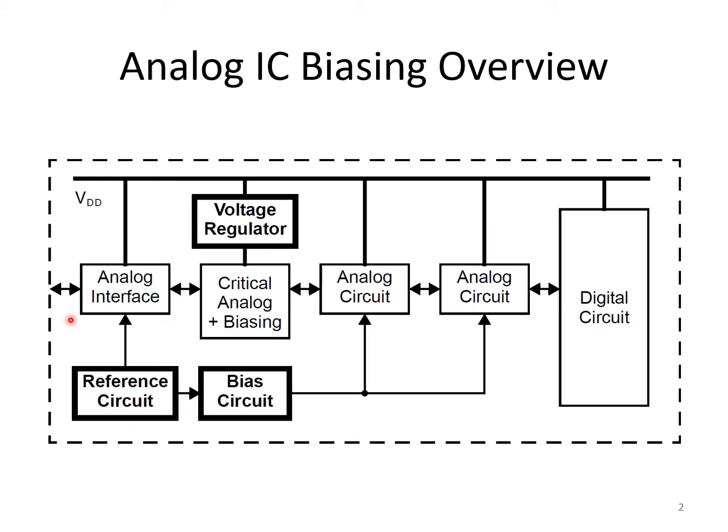So if you imagine, for example, an overall analog integrated circuit, the user of that integrated circuit doesn't particularly care what the voltage swings are internal to this integrated circuit. There might be swings of 200 millivolts in here or 300 millivolts. The user of the IC doesn't care so long as the signal levels at the interfaces, that is the I/O of the chip, are within specified tolerances.